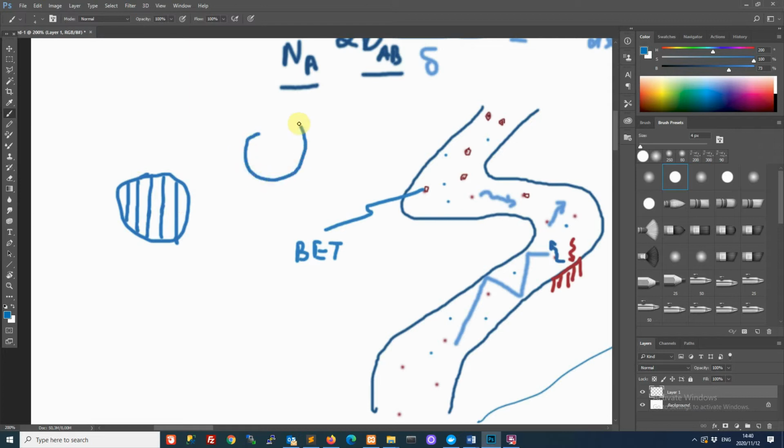You can imagine if we are trying to increase the surface area in the particle by applying stress and inducing cracks, and maybe it's through applying high temperatures and basically sintering and all kinds of crazy things going on in the particle, then our cracks are highly irregular things. And so the length of our pore is not so easy to estimate. The length might be much greater than, for example, the diameter of the particle. The length may be many, many times the diameter of the particle. And in fact, it's for reasons like this that you can get some crazy values for the surface area inside particles.